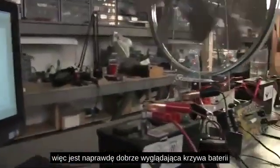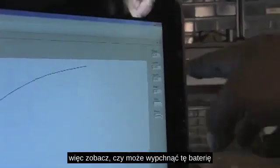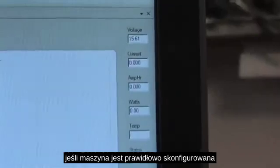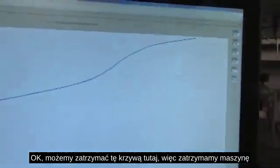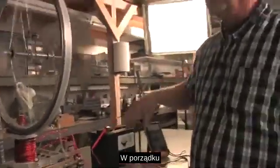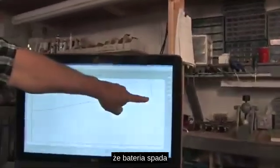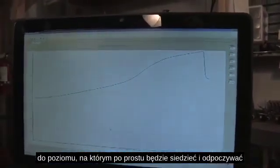So there's a real good looking battery curve. And look where the voltage is, Tony. So see, it can push that battery really quick if the machine is set up correctly. Okay, we can stop this curve here, so we'll stop the machine, because we're already at 15 volts. Now look, the battery falls down to its level of where it's just going to sit and rest.